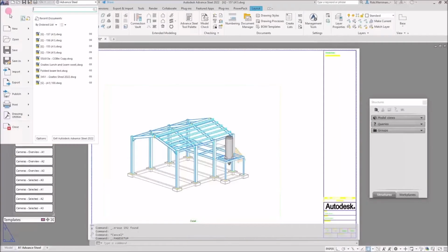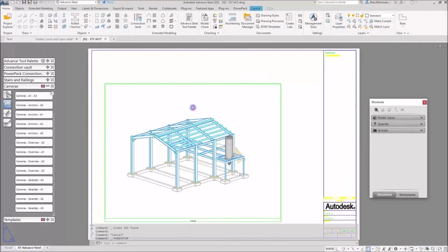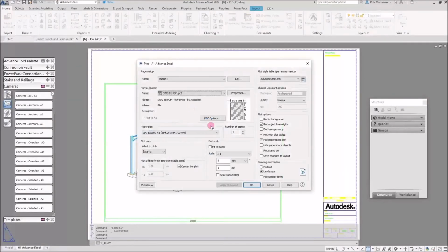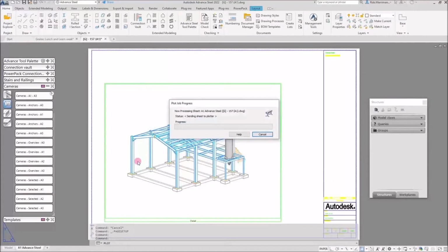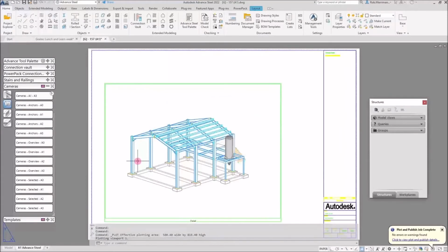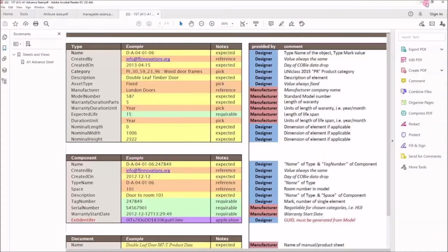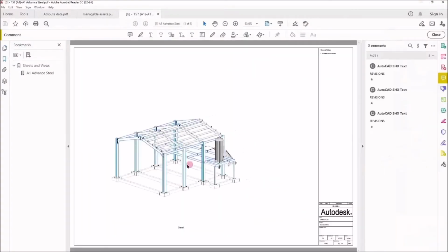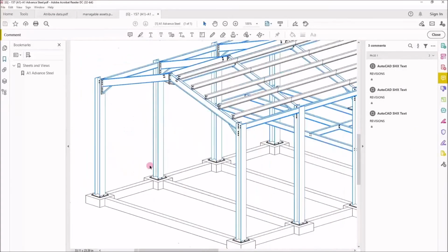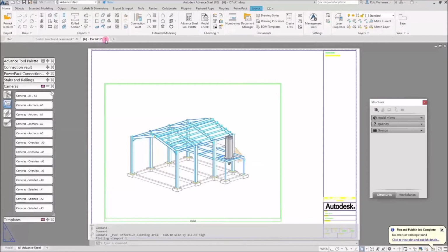If I actually go and print this, now those colors, that I can get GA colors to come through, that CTB file would be used on every single drawing. Yeah, let's just put that there for now. But when this plots, this will plot with everything else as black, but those as the blue color. So that's how we can do that.